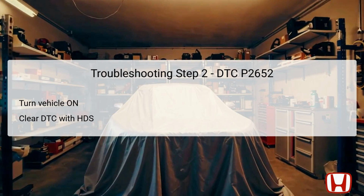In the second step of troubleshooting DTC P2652, the procedure involves turning the vehicle to the on position without starting the engine, allowing the vehicle's systems to initialize. After ensuring that the ignition is in the proper position, use the Honda Diagnostic System, HDS, to clear the DTC. Clearing the DTC allows you to reset the system and check if the error reappears, which is crucial for verifying whether the issue is persistent.